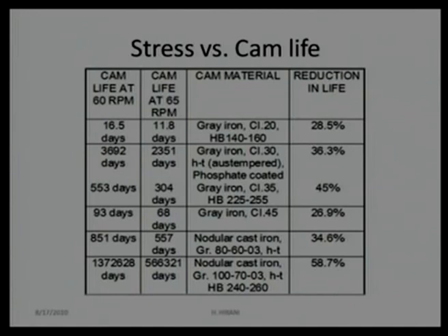In real sense, if the sliding is reduced by applying proper lubricant, obviously instead of 9% sliding, there is only 1% sliding or 2% sliding, then this life will increase. Now, if I change from this grey cast iron to this grey cast iron, which has solid lubricant phosphate coated, the phosphate itself is acting as a solid lubricant layer. That means sliding, obviously that coefficient of friction will reduce substantially. In that case, we are able to find the very high life.